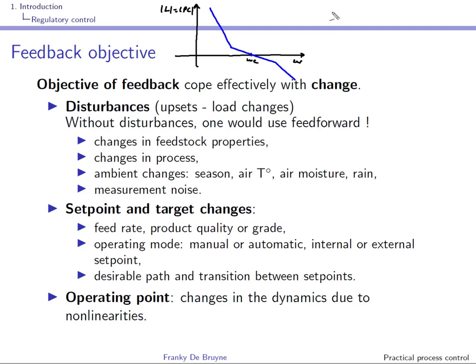Well, the transfer function from set point to PV is PC over 1 plus PC, and since at the low frequencies you have a high loop gain, in those frequencies this transfer function will be approximately 1 because of this high loop gain, and you can see here that variations of P will be mitigated by the feedback principle, right?